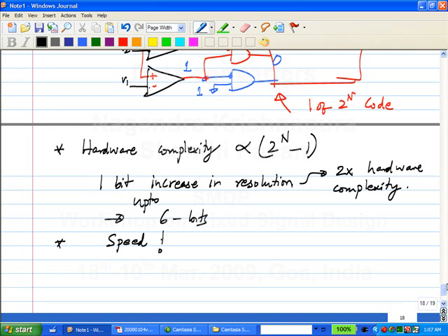The system working but not efficiently, you might be able to accept. But if you put feedback with too much delay, you understand, right? Whenever you have a feedback loop and there's a lot of delay in the loop, the loop will become unstable. Delay and phase are pretty much related, correct? So if there's a lot of phase in the loop, then the phase margin in the loop goes down, and if the phase margin becomes too small, you have instability. So in applications where the A to D converter is embedded as part of a feedback loop, you cannot take too long to decide what the input is. So a flash converter is often used even though it is inefficient, because you want the output now. You understand? Okay?